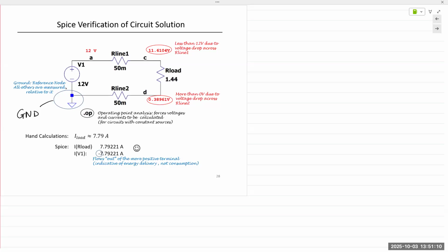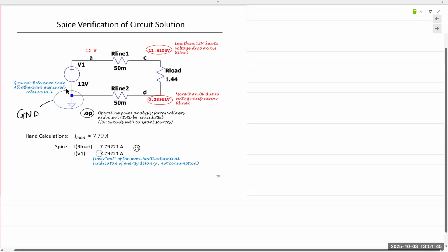This is node 001. This is node 002. Or if it's a ground node, it's going to say this is ground, GND. And the value of that voltage will also be shown, 0 volts. We can also mark the voltages directly on top of the circuit diagram. So if you take your mouse cursor and click anywhere along this line, it's going to show you the resulting voltages.